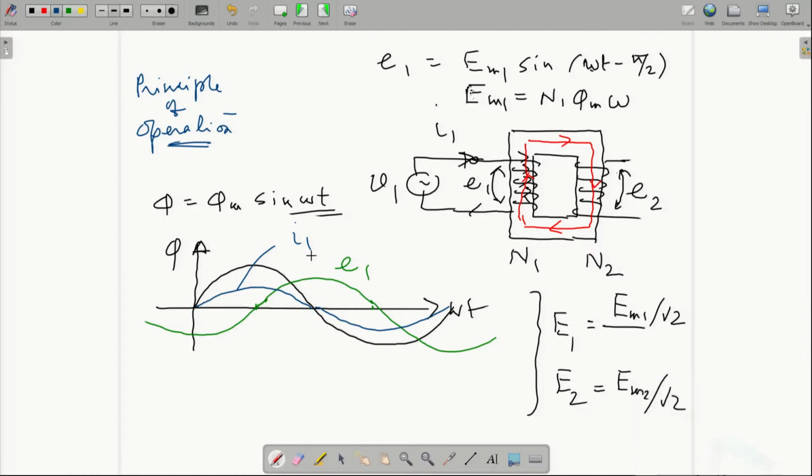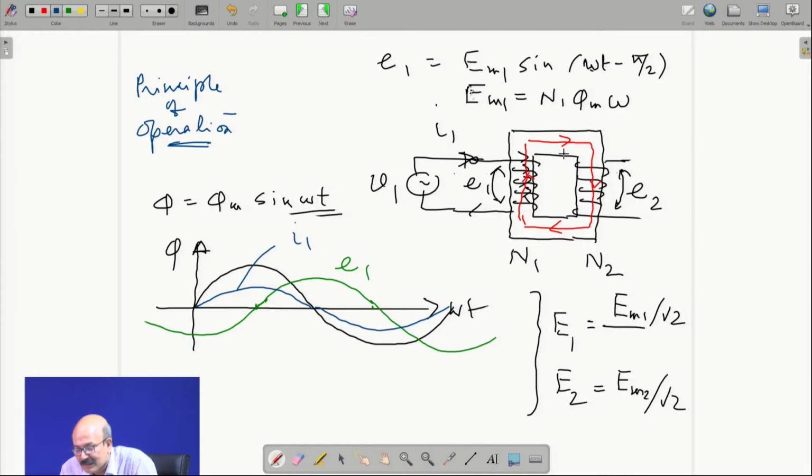The next is just a coil, and for the coil no resistance, nothing considered for the timing, no resistance, no leakage. So, current must be lagging the applied voltage V by 90 degrees. And because this is the ideal case, we have neglected all resistances, leakage reactances, loss, magnetic circuit linear.